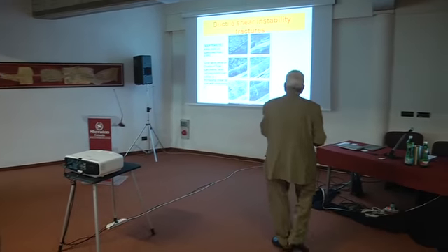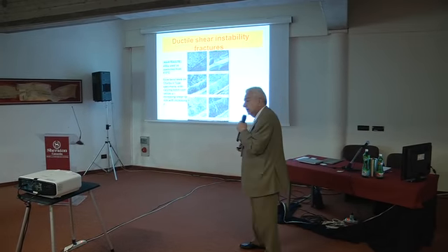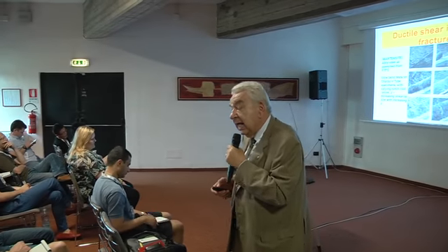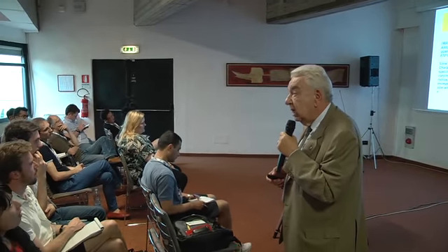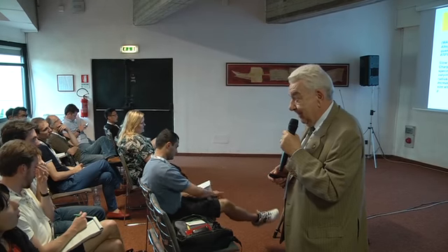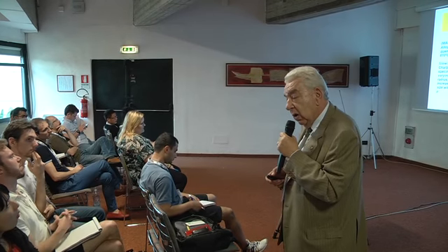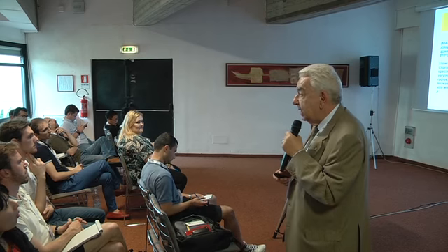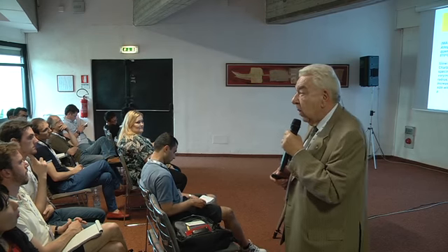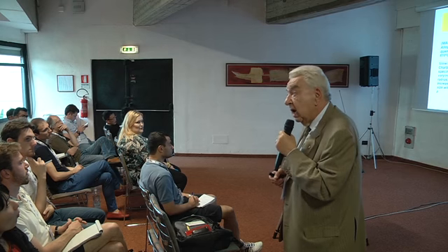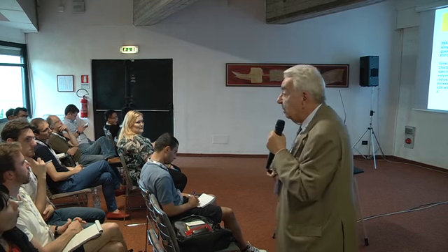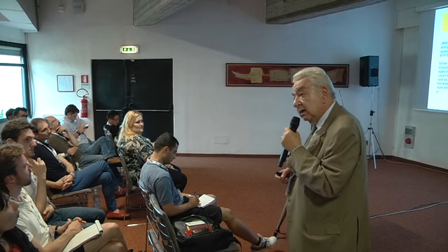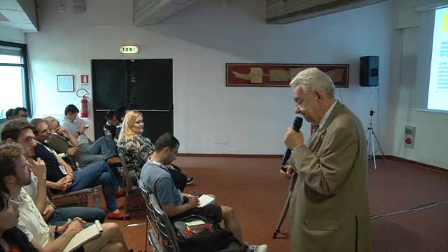We have begun to speak of shear instabilities before, but we have to consider that shear instability is a common way of initiating a fracture in quenched and tempered steels when you do not have a sharp crack, but you have a notch with finite root radius.